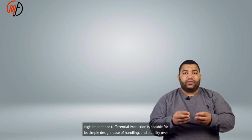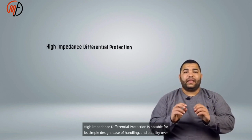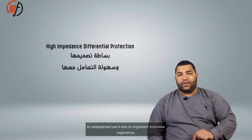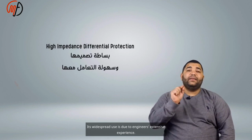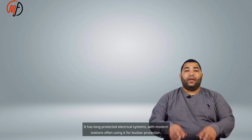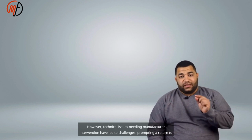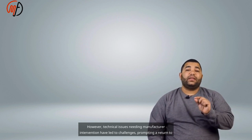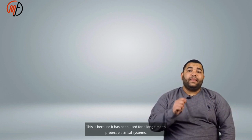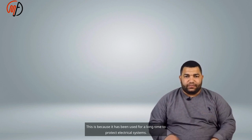High impedance differential protection is notable for its simple design, ease of handling, and stability over low impedance differential protection. Its widespread use is due to engineers' extensive experience. It has long protected electrical systems, with modern stations often using it for busbar protection. However, technical issues needing manufacturer intervention have led to challenges, prompting a return to traditional differential protection.